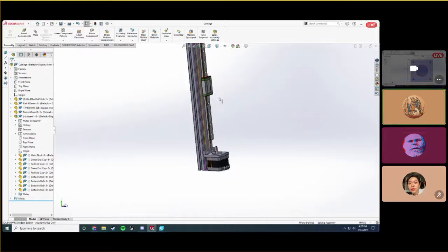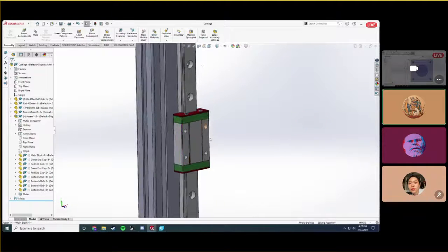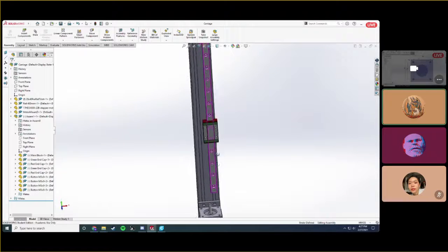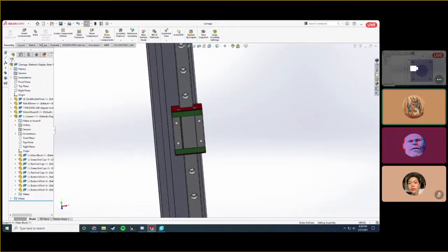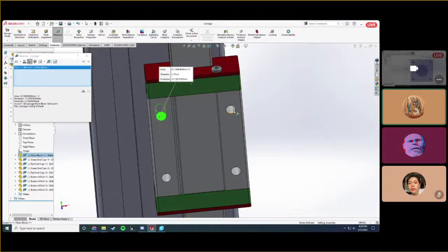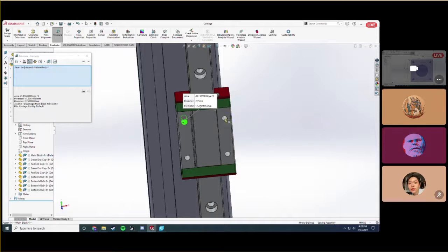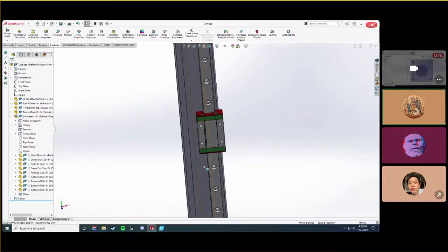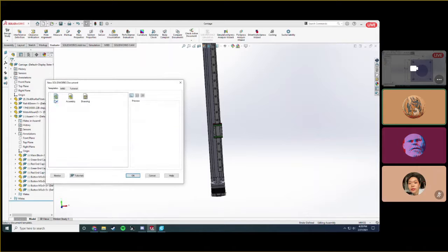Yeah. So now that we have this, let's say we wanted to mount something onto this block. Let's say we want to make a sheet metal piece to mount that on. We could do that. First, we'd need more dimensions, which is just going to be the dimensions between these two holes, 20 millimeters, and then I think it's just a square with 20 millimeters, yeah. But this time we'll make it out of sheet metal. So let's go make new part.